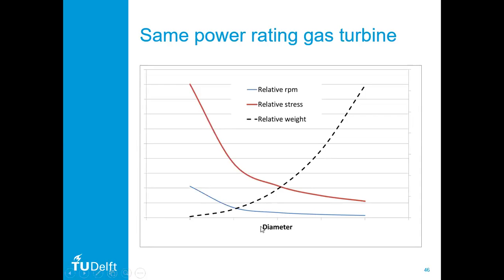Therefore, if you look at aero engines, they normally work at a lower diameter to save on weight. If you have a big gas turbine on the ground, you can have the biggest diameter possible. That's what we're running with heavy duty here. That's only limited by the rotational Mach number, so that you have a Mach number of 0.8 at the outside of the inlet compressor with the highest diameter. So here you are with the heavy duty somewhere, and here you are somewhere with your aero engines.